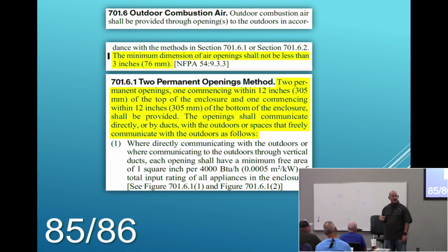So if I were to push the ceiling tile out and above the ceiling I had a vented attic, do you agree that's direct communication again? There's no duct unless you can see the duct. That's a vertical duct because I can see it. That's a horizontal duct and I can see it. If I push the ceiling tile out, that's direct communication. If I just cut a hole in the floor, that's direct communication. If I just take the door off the hinges, that's direct communication. Okay? Down below that, 701.6.1, 2 permanent opening methods.